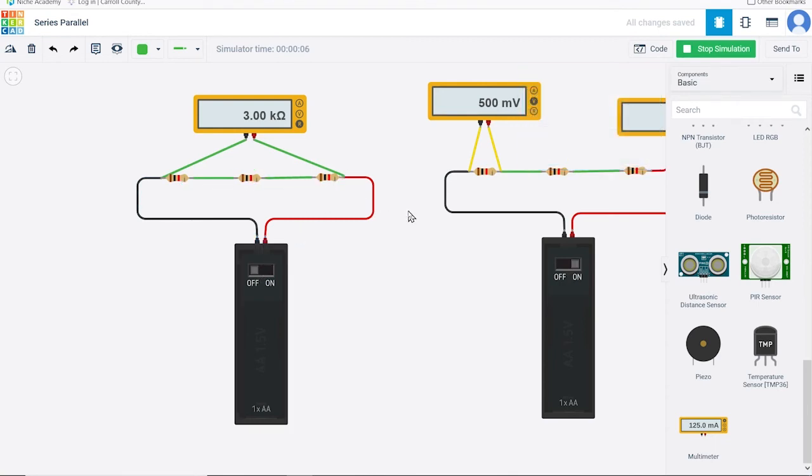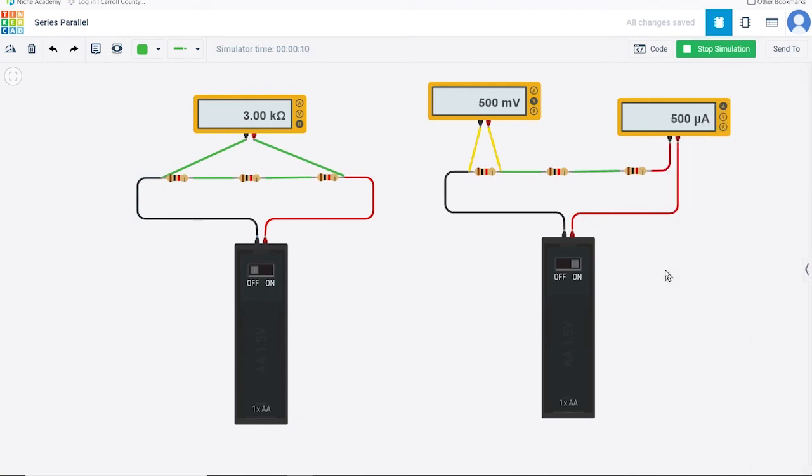One important thing to keep in mind when working with Ohm's law are the scale of units surrounding each variable. For example, resistance is calculated in ohms, so a 1K resistor would be 1,000 ohms, a 100K resistor would be 100,000 ohms, and a 1 megohm resistor would be a million ohms. Current in most Arduino projects is given in milliamps or microamps, that is thousandths or millionths of an amp. Ohm's law needs amps, so be sure to use the right number of decimal places when plugging numbers in.